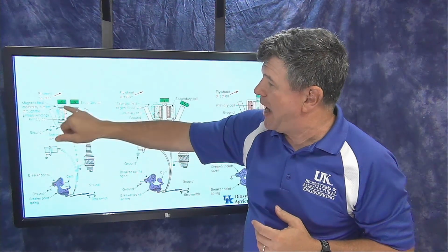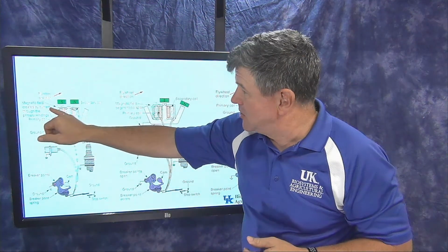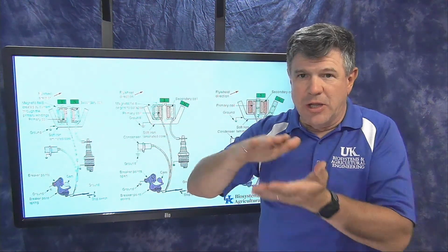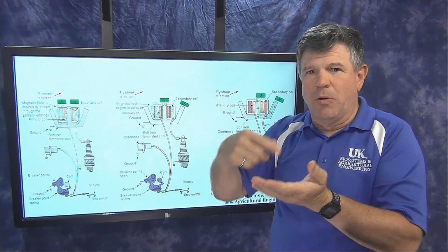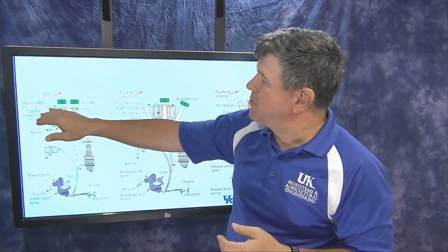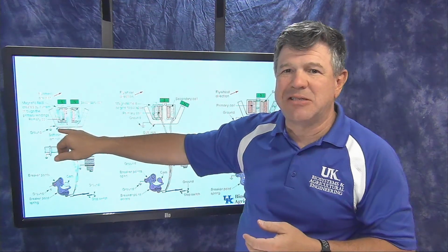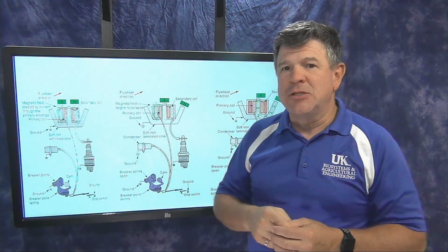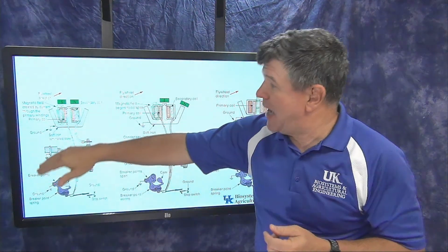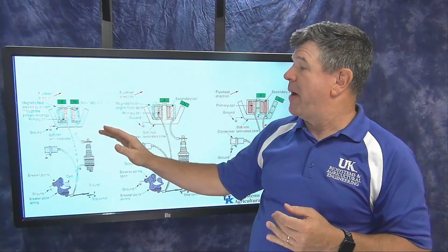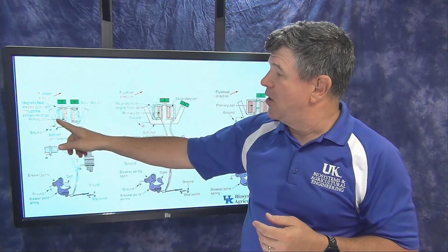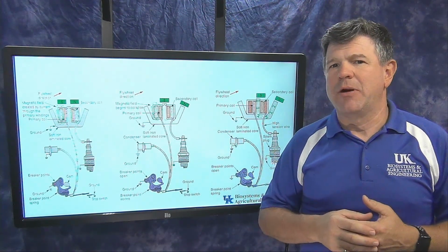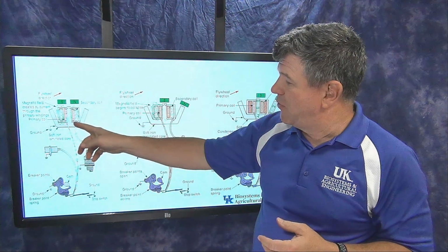When those magnets go past these coils of wire and the associated armatures, so we call these big things the armatures here, they're usually layers of laminated metal that the coils are wrapped around. But when those magnets go by there, they start to make things happen. They make electrons move around, and I start to get current flow. Everything is going to happen in a split second as those magnets come past. So as the magnets come past, the first thing that happens is that it creates some current flow in the primary side of that transformer, the primary side of that coil.